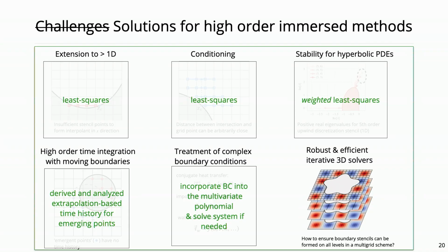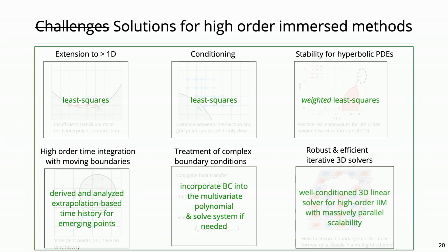We have found an effective way to incorporate complex boundary conditions, which is basically to solve a linear local system of equations for every control point that gives you the Dirichlet boundary condition that you need to move forward. And we have developed a well-conditioned 3D linear solver for high-order immersed methods with massively parallel scalability.